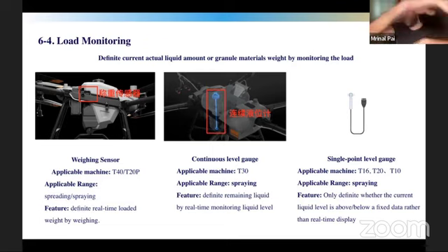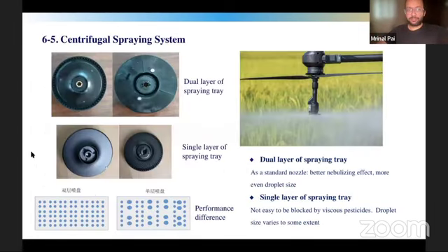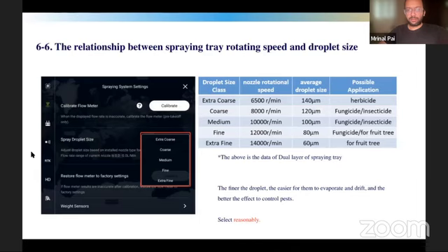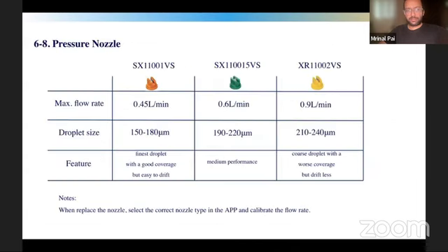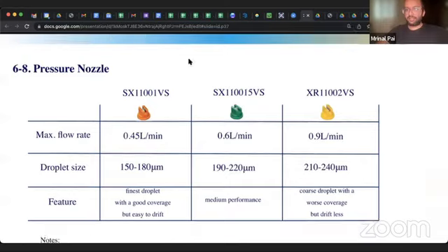So if you're flying 5 acres, you've planned a mission, you've taken the boundary, and in between, if it runs out of liquid, it comes back and lands where the operator started the flight. If it runs out of battery, it comes back and lands. So either he changes the battery, or refills the tank, and then continues, right? He presses continue on the app and it will continue flying. The different technicalities and different nozzles allow different flow rates. All of these components put together form the drone.